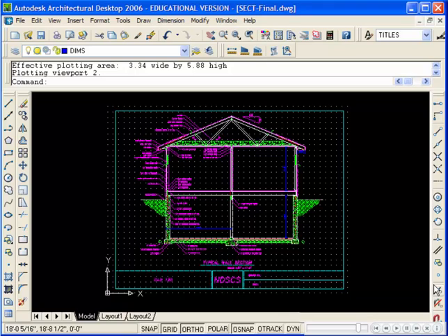This drawing was designed to plot on 22 by 17 paper, okay, or C-size paper. And when you're plotting it, I've been plotting at just letter size, 8.5 by 11, so if I did the entire drawing, I'd have to scale it to fit the paper, so I did that. And then if I was taking small portions of it, whether I used window or view, then I was scaling it to the exact scale of the drawing, which was 1/2 inch equals a foot. And it was coming out and it would fit on 8.5 by 11 paper.